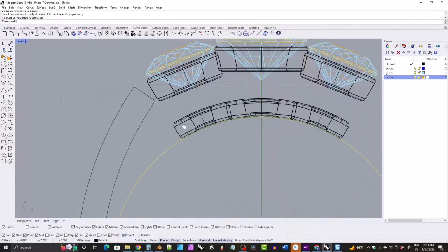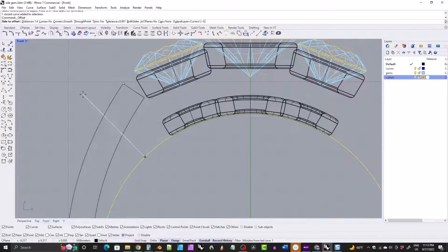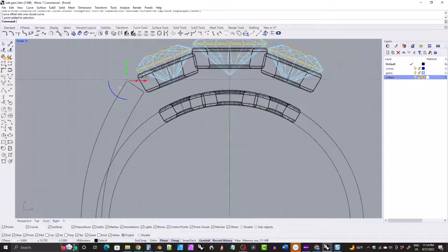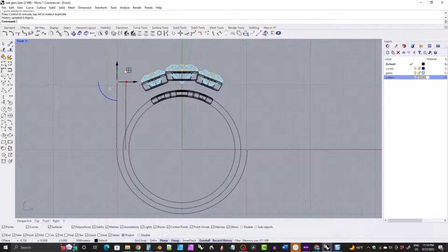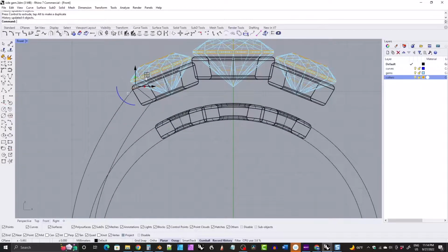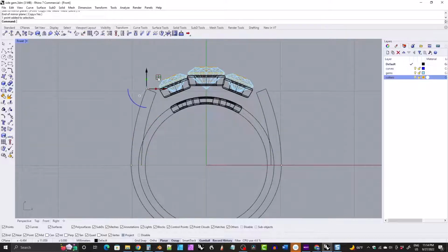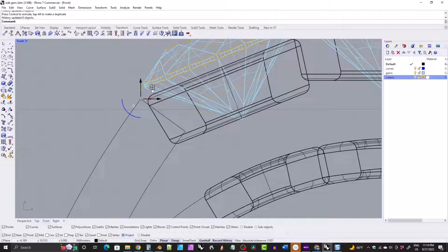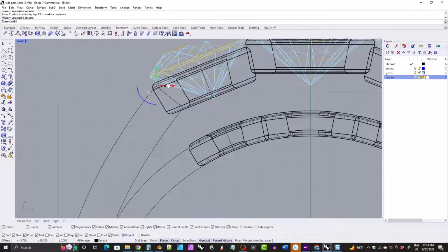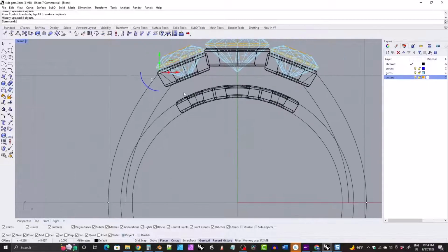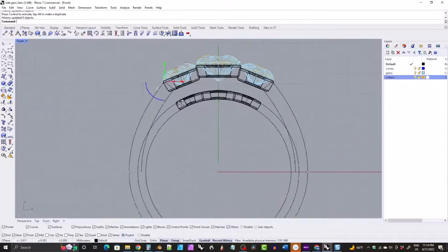And then we'll offset the sizing circle by 0.9. And then we can move this point. And we have a history enabled sketch or guide to how we want this shank to be. I'm going to pull it over here for a minute and we'll select these three lines and mirror them over to the other side along the center axis here. So I'm just going to move this point in here. And that looks about right as far as our shank is concerned.